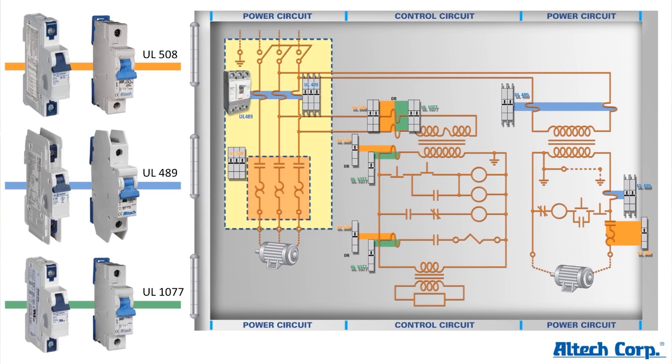What that enables is that you have a bank of breakers, and you don't need to shut off the main to switch off your load or service your load downstream. If you have a bank of 1077 supplementary protectors, which we offer as well, shown on the bottom there with the green line through it, you would have to turn off the main to then service your load downstream, so as not to violate UL or the code.